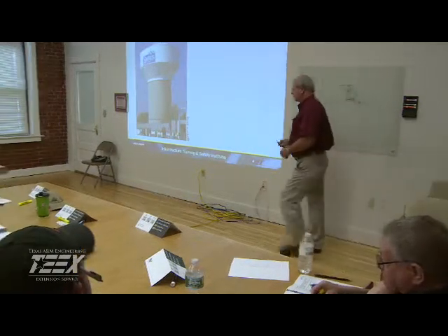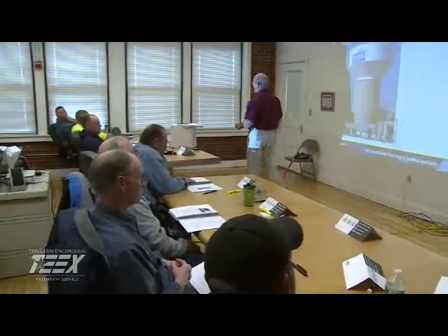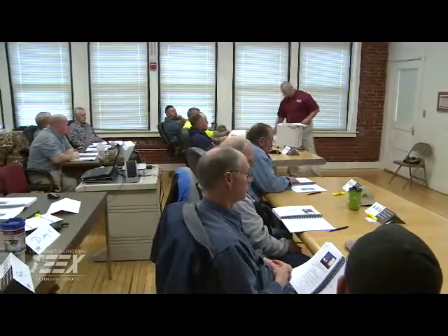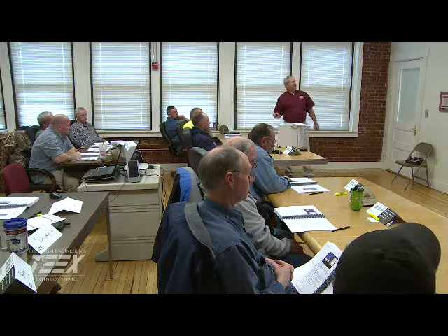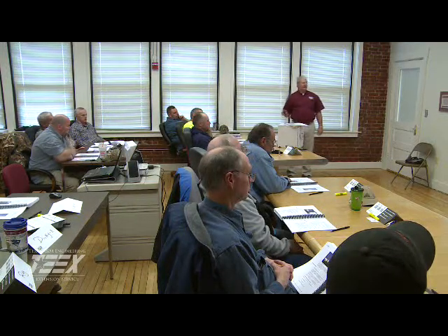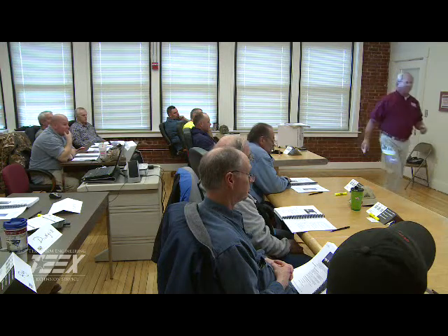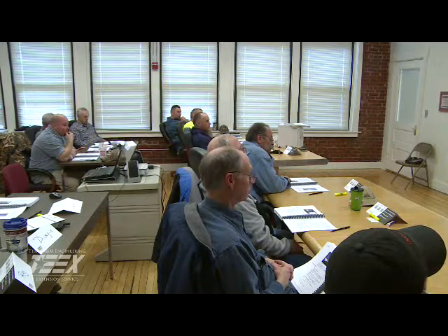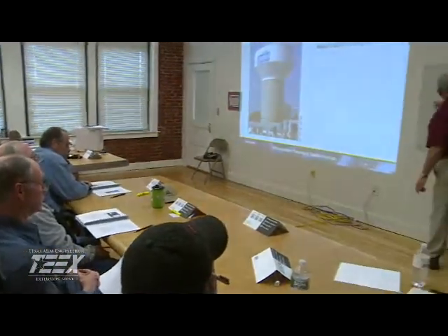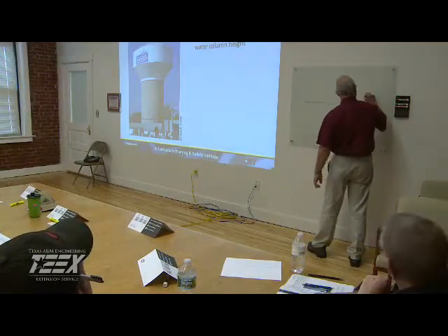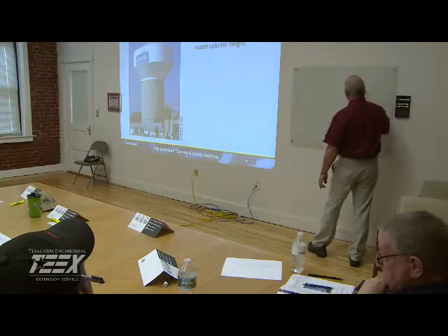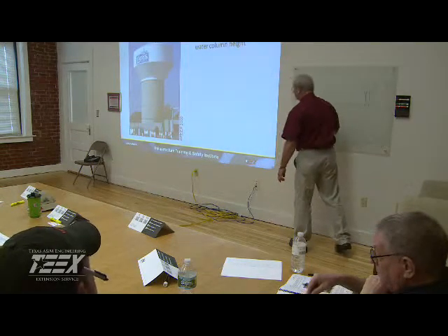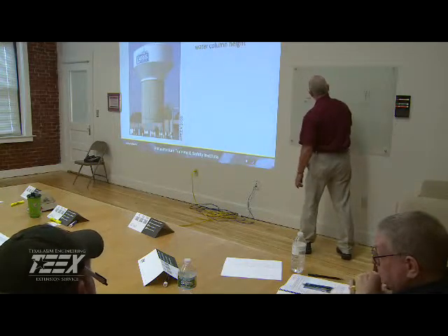All right. So the people in the valley are going to have higher pressure than those people up on the slopes of the hills. All right. And pressure is maintained by water column height. And I'll put this over here too. When we talk about the hydraulic gradient, let's just say this is the city, and over here I've got an elevated storage tank. And over here I'm going to have a ground storage tank, and it's being filled by a well. Okay, now here's my town in between.